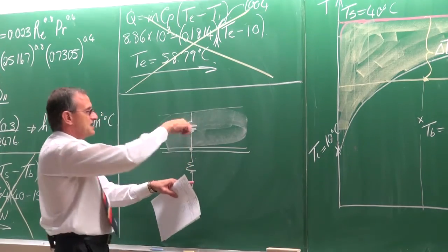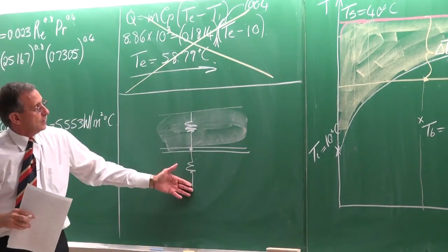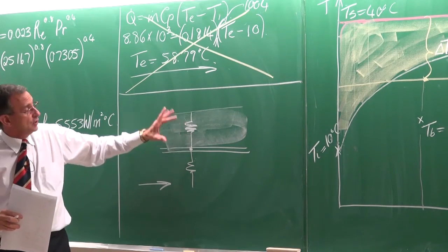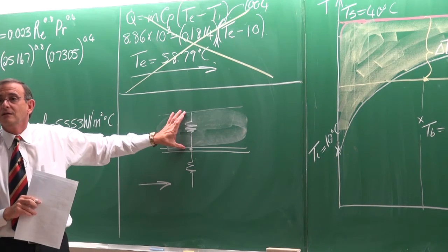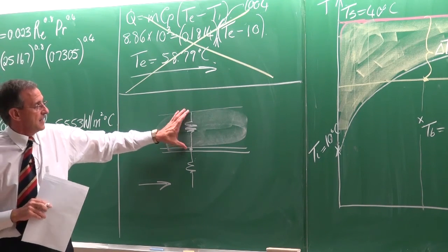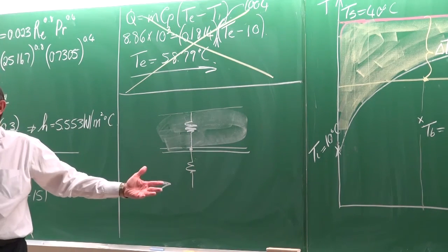These three resistance terms will determine the heat transfer rate. So if you put insulation there, you want this resistance term to be very, very high. Because if the resistance is very high, then there can be no heat transfer through it. And that is the idea.